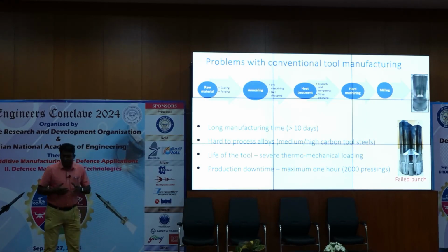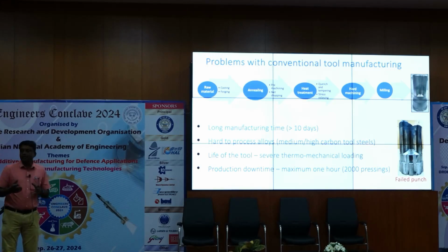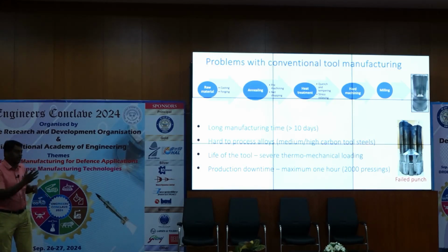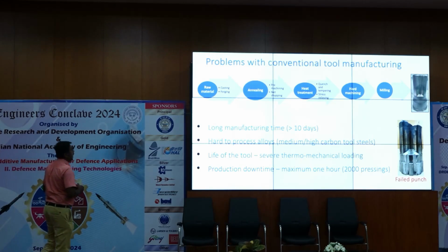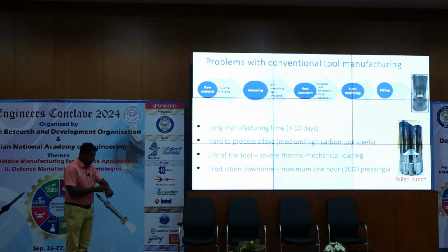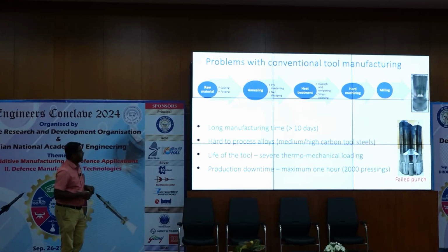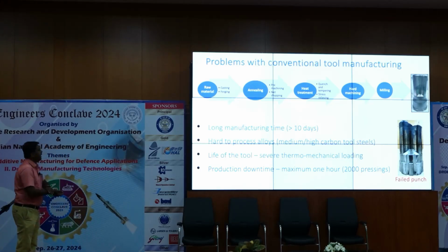Right, so in order to enhance the life of these punches, we need to make sure that the punches are not heated up, especially in hot forging, so that we can mitigate the associated thermomechanical fatigue. You see the failure of the conventionally made punch.